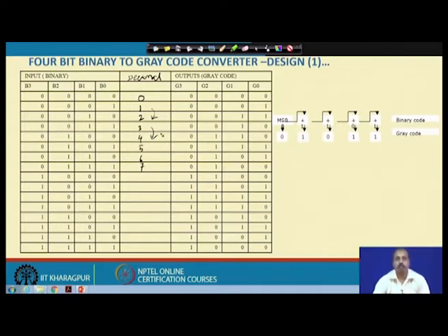Now, this is sometimes not very advisable, particularly in applications like communication, where we want the successive values not to flip many times. Also, when we have integrated circuit chips, VLSI chips, with a set of signal lines running, in successive time instances they will assume successive decimal values. So it is expected that those bits will not flip much from one value to the next.